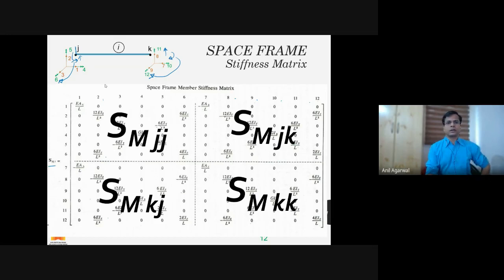So one thing we discussed, for example, you can identify torsional behavior here, separate the torsional behavior from axial behavior, from flexure in one plane. So 2 and 6 is flexure in which plane? You can call it plane 1, 2. So flexure in plane 1, 2 is given by degrees of freedom 2 and 6. Similarly, flexure in plane 1, 3. This is 1, this is 3. So flexure in plane 1, 3 will be given by deformations in 3 and 5. Okay.